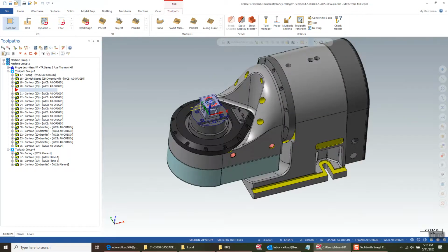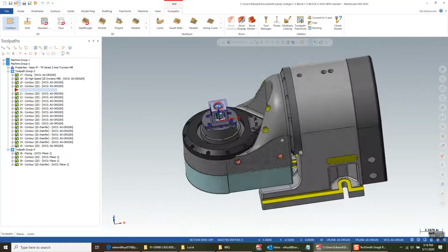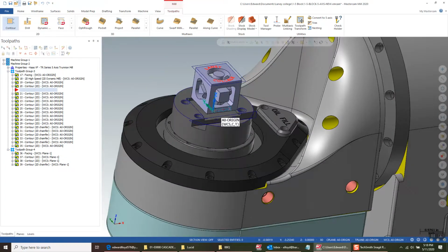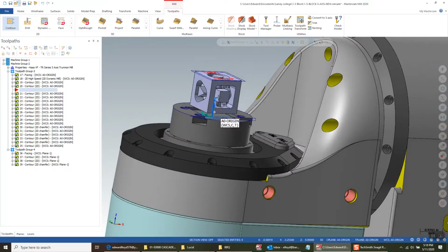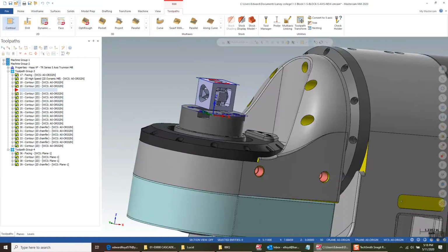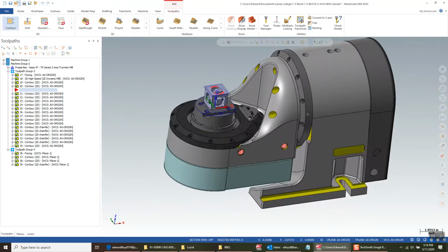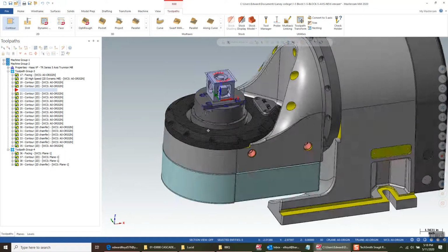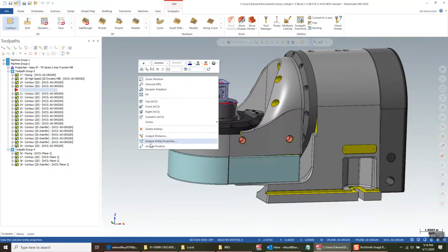All right, so this has got the whole ball of wax. It's got the 5th axis unit and everything in there. So you can see that my plane is down here. See, my A0 origin is down there sort of inside the part. So how is that? Well, the documentation of the unit gives you the location of the center of rotation. So in X and Y, it's just going to be the center of the platter that spins here. But for Z, they give you the number, and I can show you.